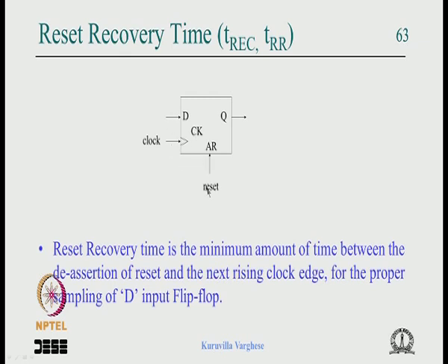But when you remove it near the positive clock edge, near the setup time, this can get into metastability, because two drives are there and this doesn't have enough time to drive it to the proper value. So this can get into metastability. So this has to be met.